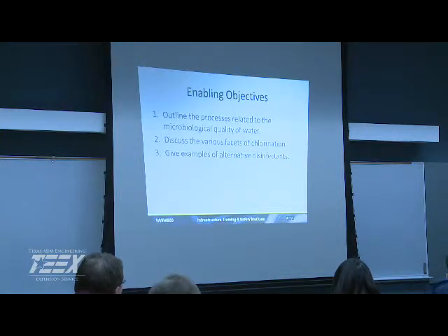Arizona's using a lot of ozone. Real expensive process, and you can't use it for final disinfection, but they're using it as part of their pre-treatment program to help with their disinfection byproducts. Real expensive, a lot of technical expertise required for it, but that's what they're using to incorporate into some of the real big systems out in Arizona. So it's interesting to see who's doing what.